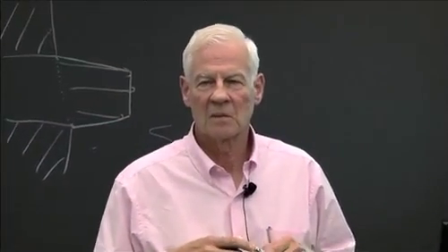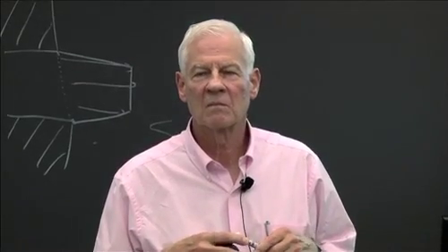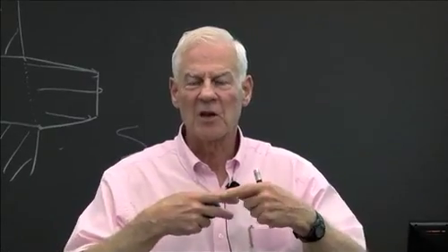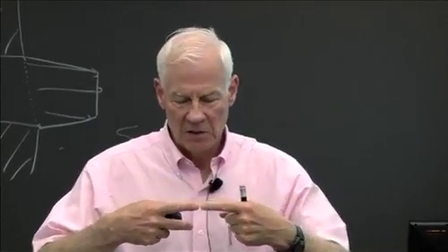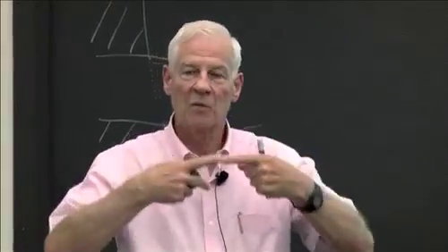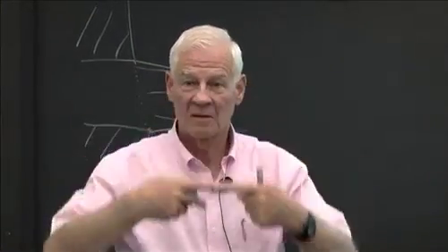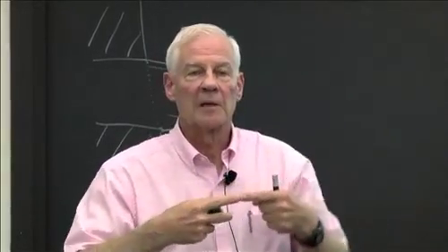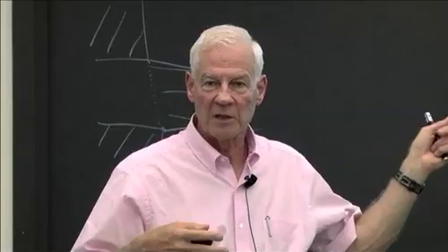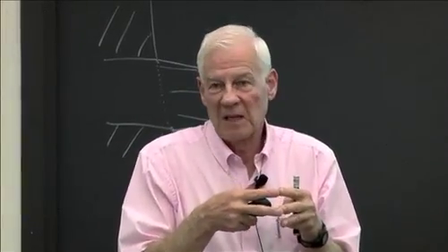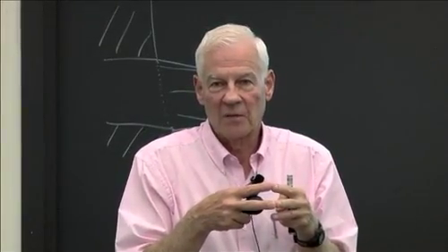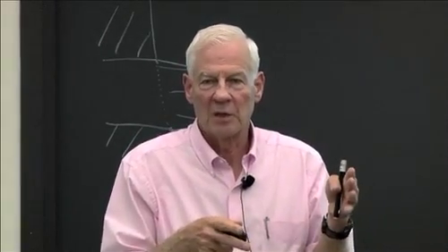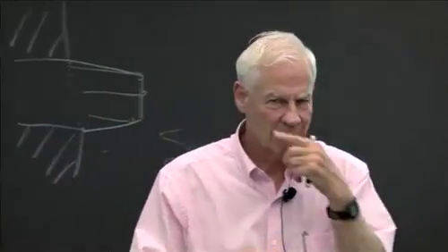How do you extend this technique from point-based to planar-based measurement? Okay. What I think you mean is along the line, a single line. How do you extend this from one line to many lines? Well, we've done this by scanning one beam this way. We've also done it by splitting the beam. The one I showed you from ATK, we do 3 beams simultaneously because we only had a couple of milliseconds. If you have enough power, you can split the beam into as many beams as you want, but you have to buy a detector for every beam.